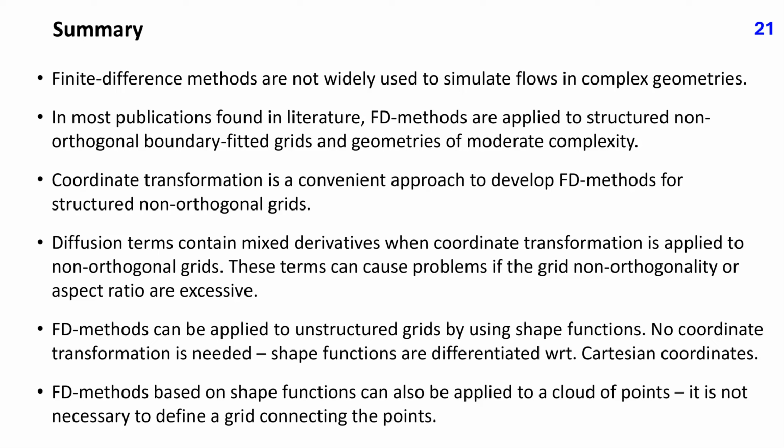Here is a brief summary of this lecture. Finite difference methods are not widely used to simulate flows in complex geometries. In most publications found in literature, finite difference methods are applied to structured non-orthogonal boundary-fitted grids and geometries of moderate complexity. Coordinate transformation is a convenient approach to develop finite difference methods for structured non-orthogonal grids. Diffusion terms contain mixed derivatives when coordinate transformation is applied to non-orthogonal grids. These terms can cause problems if the grid non-orthogonality or aspect ratio are excessive.